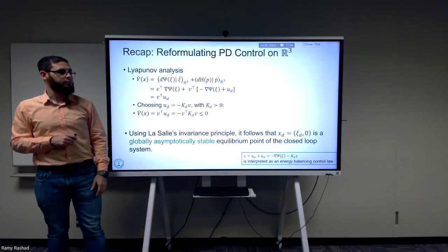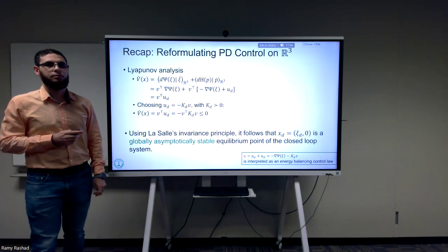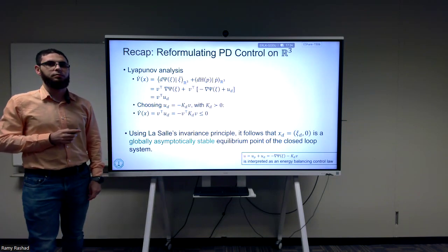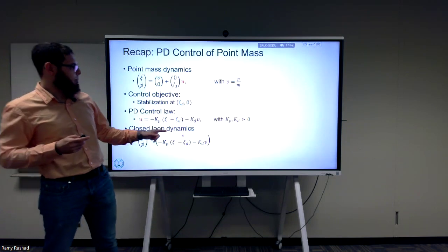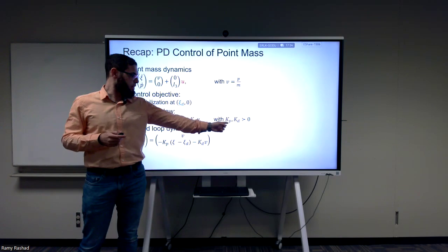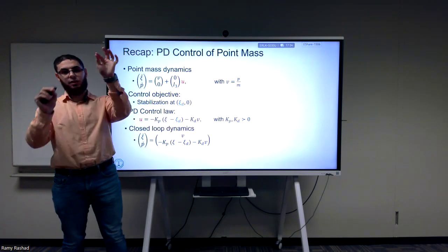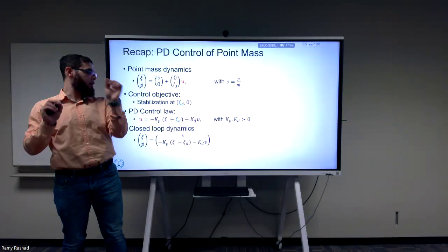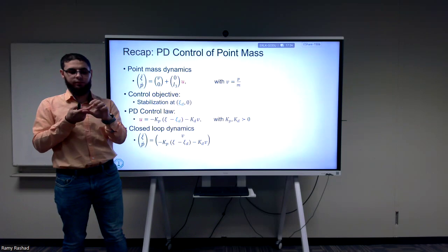Any question? Yeah. For QB and PB, they are matrices. This is because for x direction, y direction, z directions work. If you go back even to the standard proportional PD controller, you can choose KP to be positive definite, which means that they're going to have some stuff on the diagonal. So this will relate how the X error changes with itself.